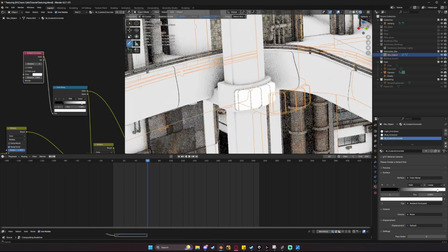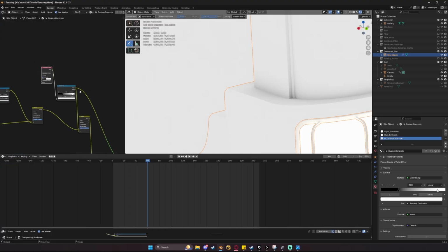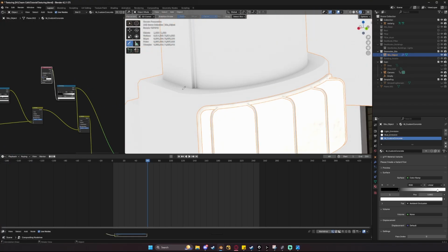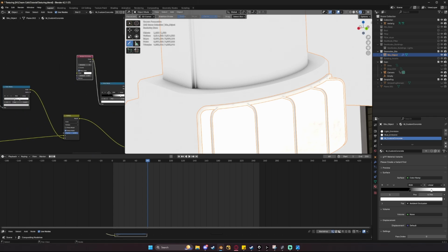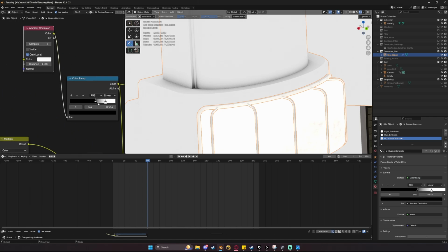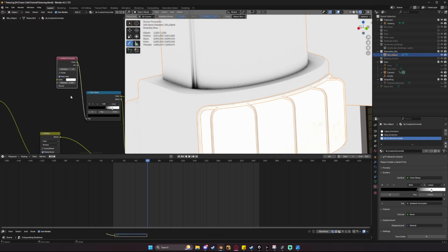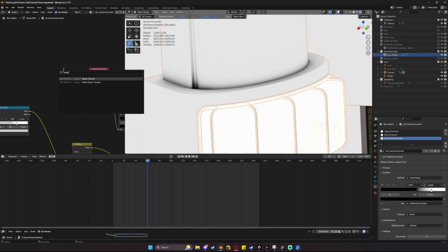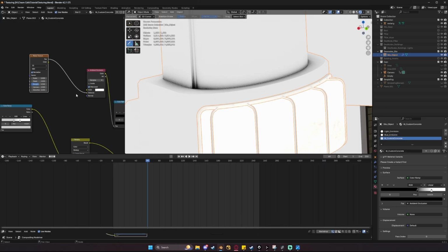Now, something we want to avoid is things like this, where we're going to essentially be duplicating the shadows that we talked about earlier. We really want to just create areas of dust buildup. So as I crunch this up, I've checked this only local box so that doesn't happen. Now, no matter how much I crunch this, however, it's never going to really look like dirt. It's just going to be this linear gradient coming from our source. And one of the ways we can add variation is we can add in a noise texture and plug this into the distance of our ambient occlusion node.